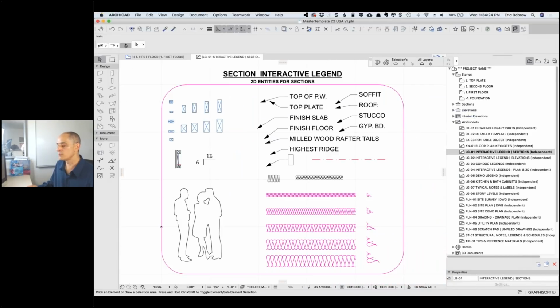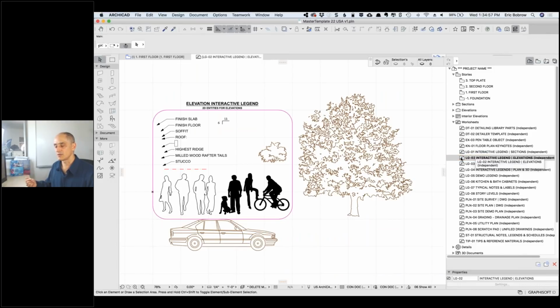But an interactive legend, if I go here, what are these? This is basically a group of elements that we can show in the background behind or in conjunction while working on a section, and then I drop it and say we're going to put in some insulation or put in labels with specific text. So if you eyedrop a label and then you go click on the label tool, it'll have that already preset. So you can have some common things in here. This is something for eyedropping, so you interact with a legend as opposed to the ones that you're going to just place on the sheet.